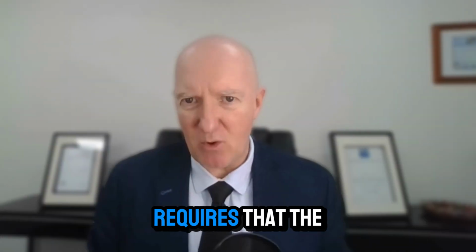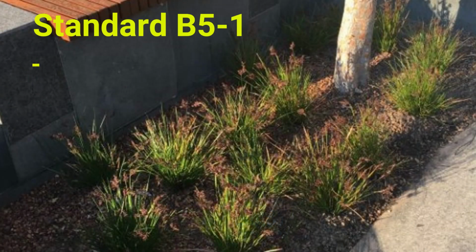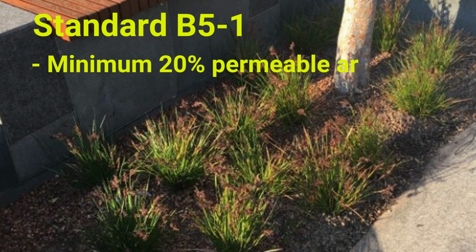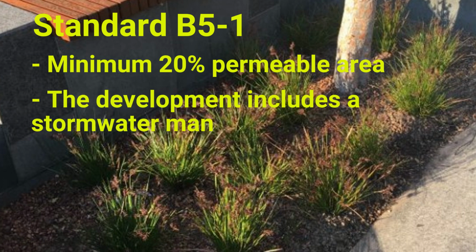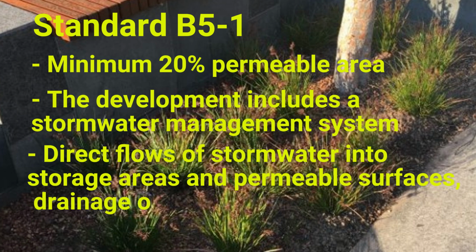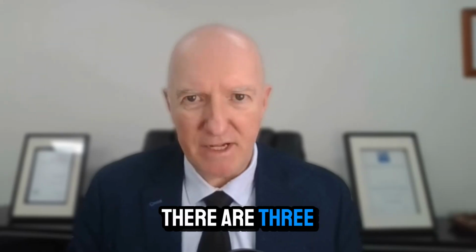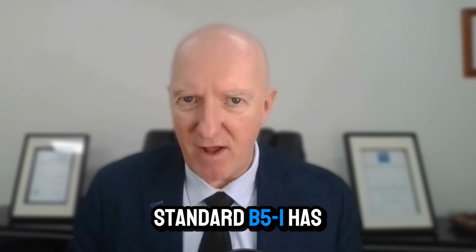The standard still requires that the site area covered by pervious surfaces is at least 20% of the site, and in addition requires the design and implementation of a stormwater management system that is designed to direct flows of stormwater into treatment and garden areas, tree pits, and permeable surfaces, with drainage of residual flows to the legal point of discharge. There are 3 steps to demonstrate that Standard B51 has been met.